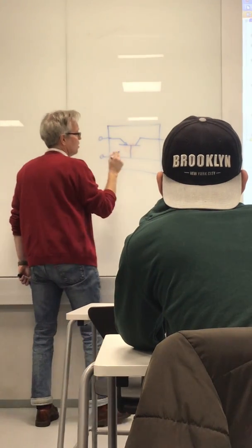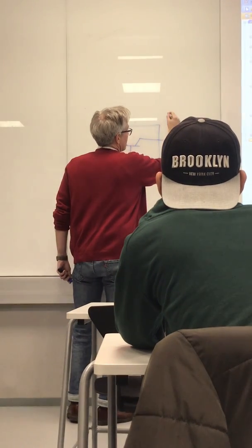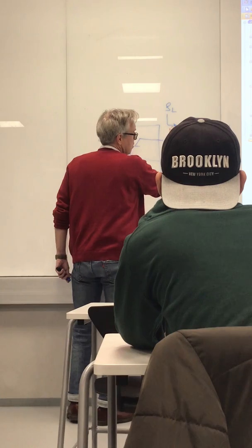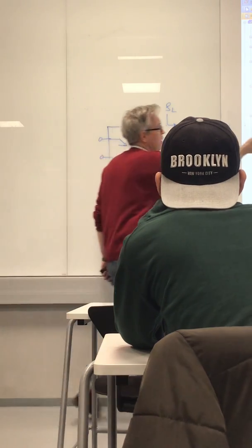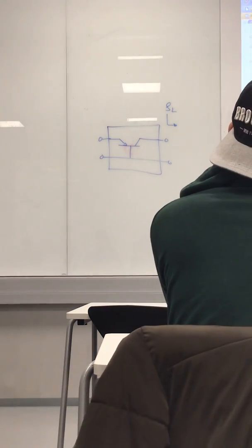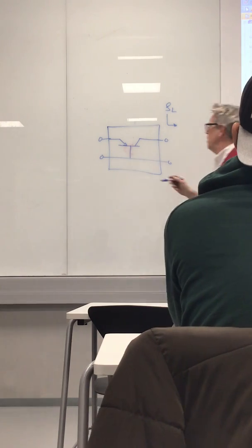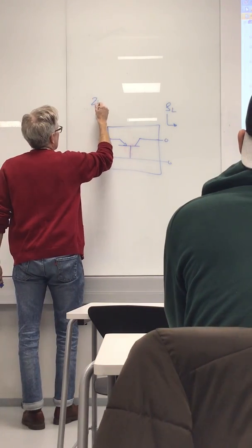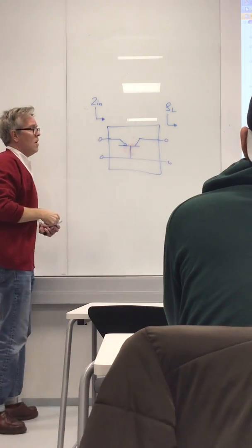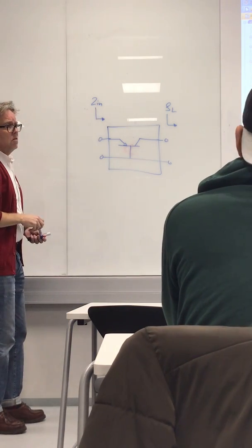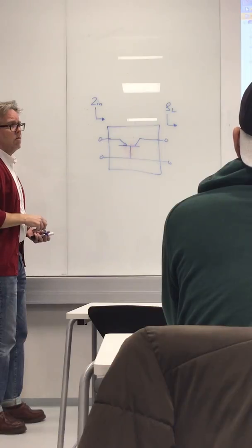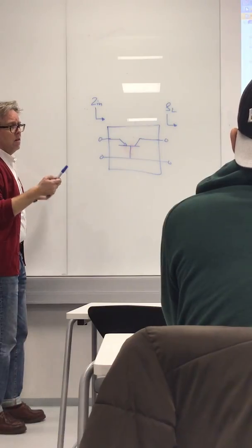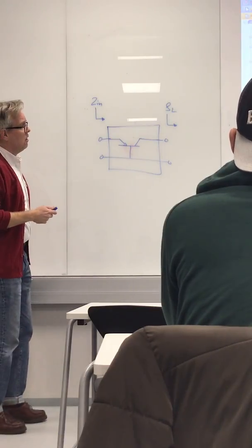The situation is this. When I select rho L from somewhere in the unstable side, then the real part of the input impedance should be negative, and then it should be possible for us to create an oscillator.